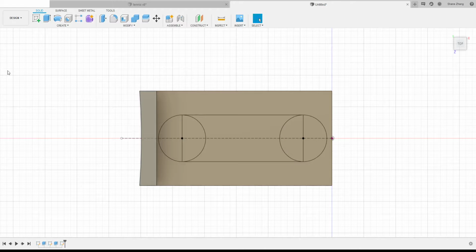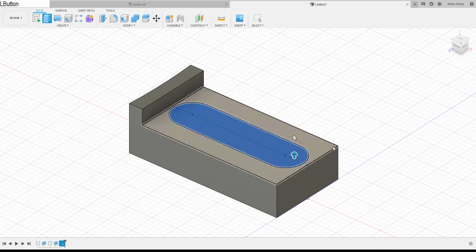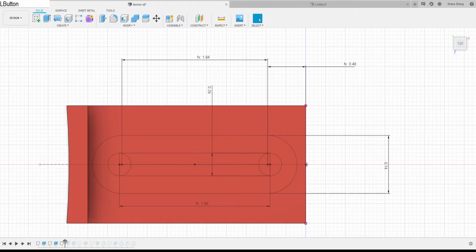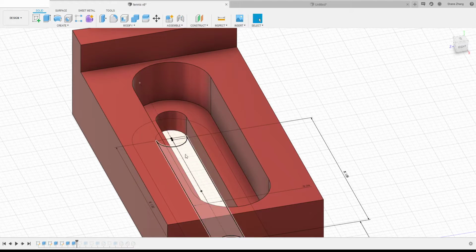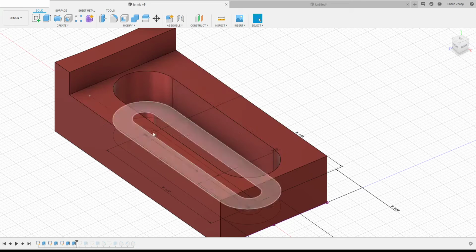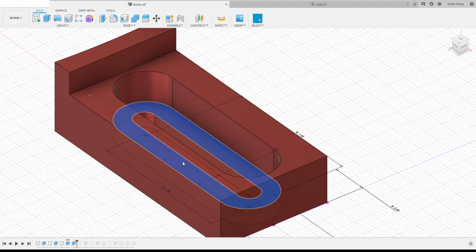And I want to see the body. Yeah. So we'll make the mill cut, extrude. Now when you do extrude, you're gonna have to click a little bit more. Let's see the distance here. Because in this model I extruded a kind of weird way. My sketch is at the bottom and my extrusion is actually not from the same plane, not on the bottom plane. It's actually a little bit offset from the sketch itself.